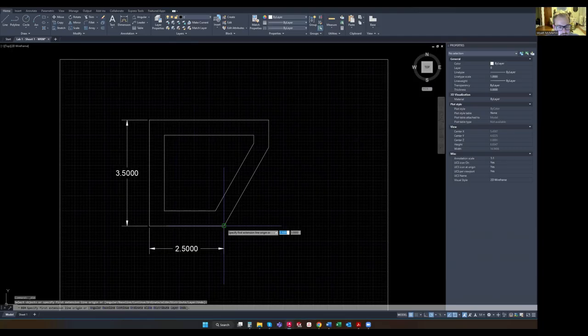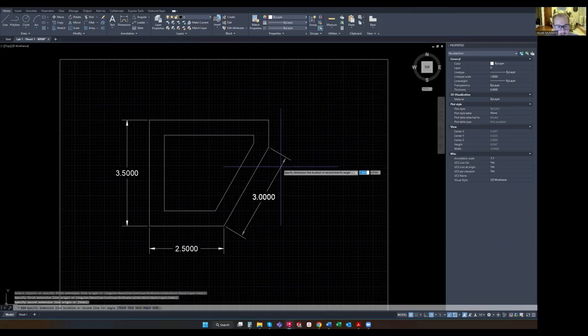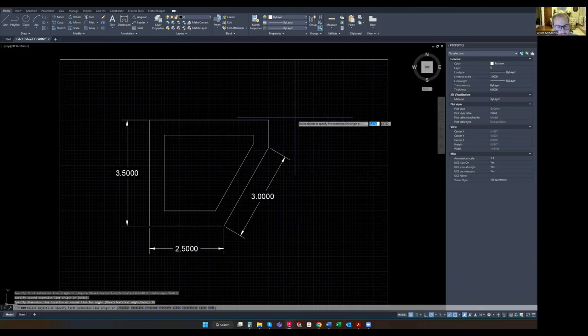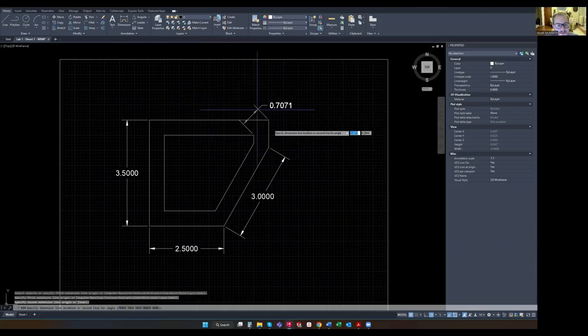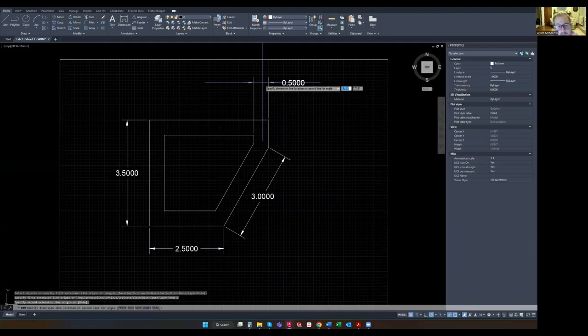And we are going to grab this 3-inch dimension from here to here. And you can do the same thing, even though it's on an angle, I can type 0.75, enter. And then we're going to grab a dimension from here to this corner. And instead of dragging it diagonally like this, we're just going to go straight up. If you go to the left of the leftmost leader line, it'll go back to the angle. As you drag it around, you see it'll try to intuitively dimension what it thinks you're trying to dimension here. So we're just going to come straight up and type 0.75, enter.